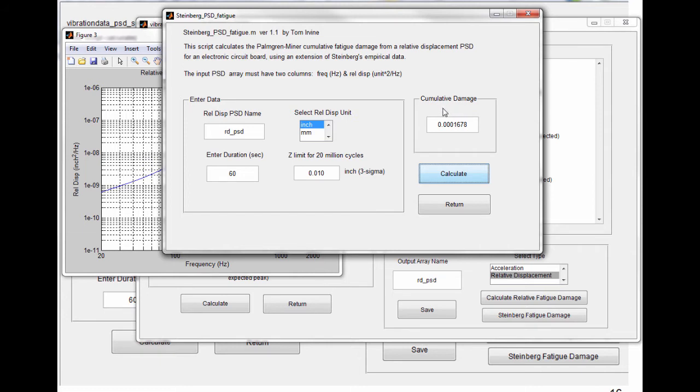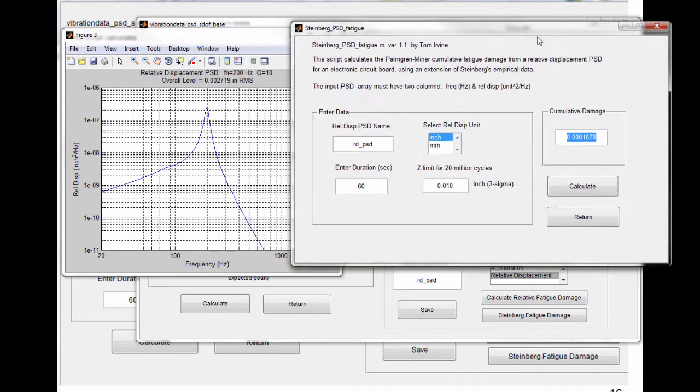And the more I think about that, the more I think maybe I need to go and put something like that as a text line somewhere in this dialogue. So that's my own little action item. So in other words, we're fine to go 20 million stress reversal cycles with plenty of margin to spare. But let's think a little bit more about that cumulative damage value.